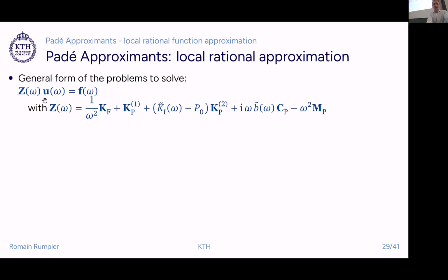Essentially, what we got to see up to now is this type of problem to solve, right? Regardless of the type of the system matrix that you have, if we have poroacoustic problems, it may have this form with a complex frequency dependency, and we showed here that we could write it in terms of a combination of frequency-independent global matrices that are then recombined by a range of functions more or less complex in terms of frequency dependency.